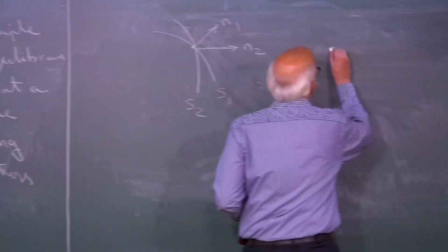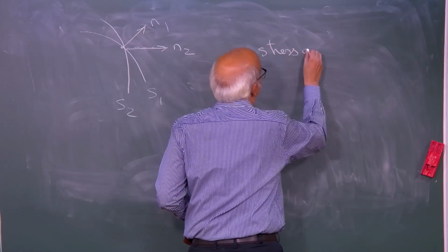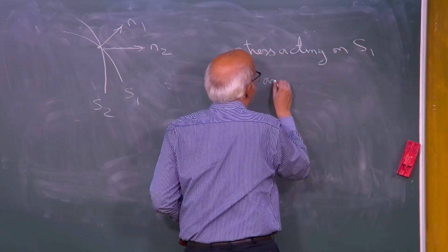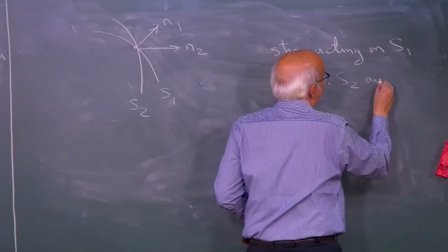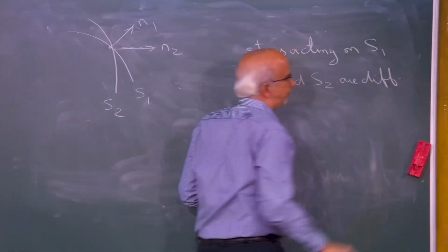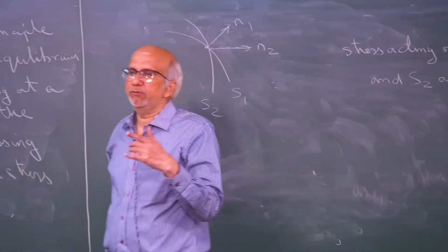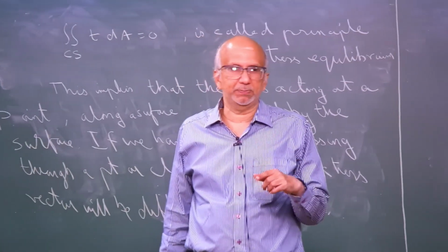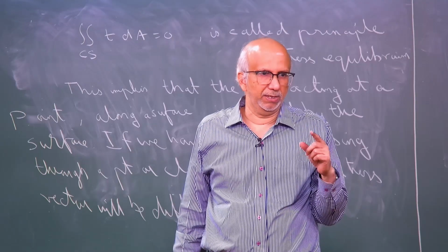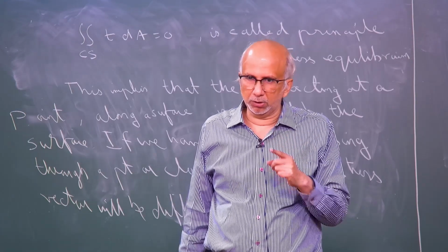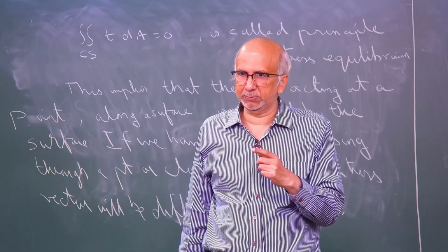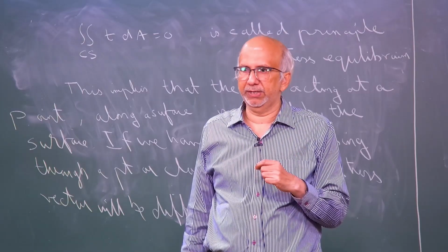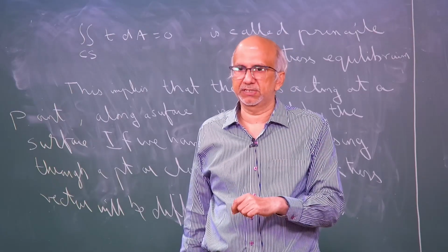Stress acting on S1 and S2 are different, and therefore when you try to specify the stress, you have to specify the surface, which is normally done by specifying the outward normal. When you talk about specifying the stress, you specify the surface by the outward normal direction and the direction of the stress itself.